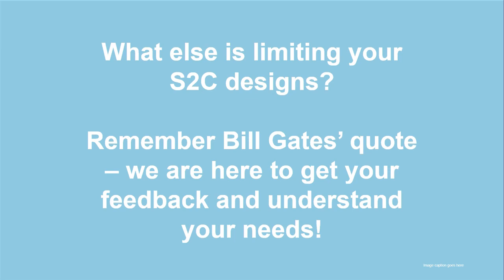Anybody else? It seems easier to use the overstrength because it's quicker, versus trying to find the ductility in the base plate. You can use standard size, big loads with a redundancy from an overstrength policy. It's a simpler approach, but you end up with larger base plates. Okay. Thank you. Anybody else?